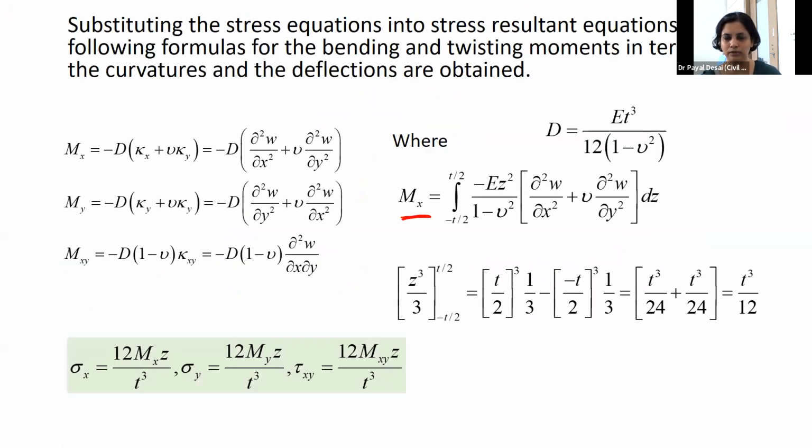And similarly here also, if I try to use my Hooke's law, sigma x, and you may try to replace the moment curvature relation, that is these three equations. If you try to replace, you get actually integration, I mean there is integration involved here. I have shown this one example of how to integrate this. When you integrate it, in the process you get something like this kind of term, and this is very similar to the kind of term like EI, that is bending stiffness, flexural stiffness.